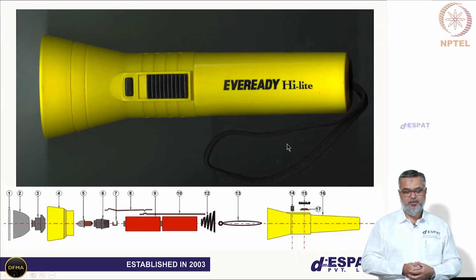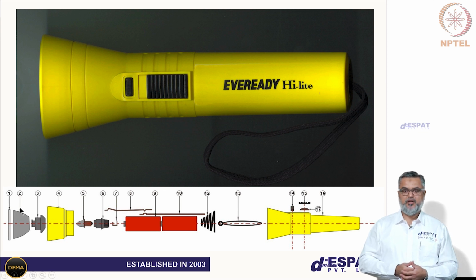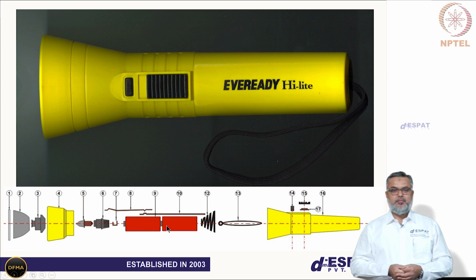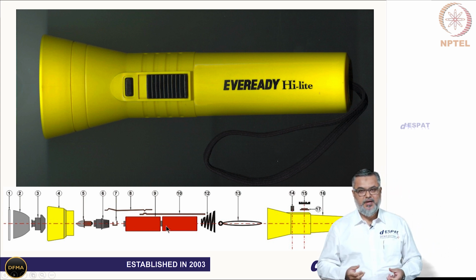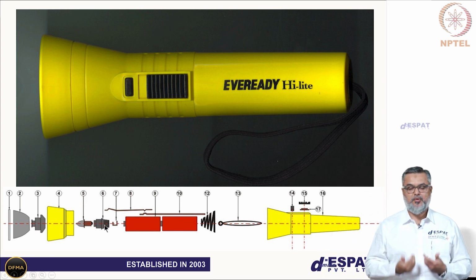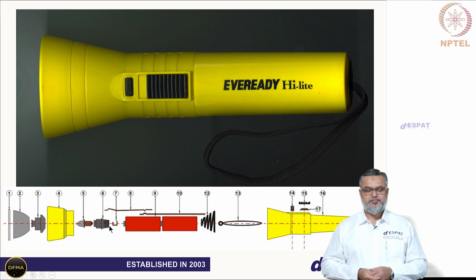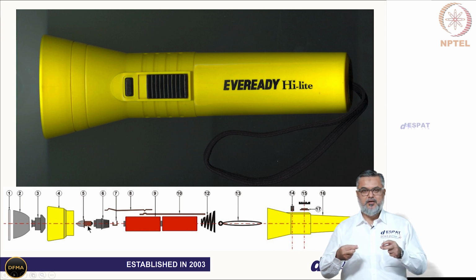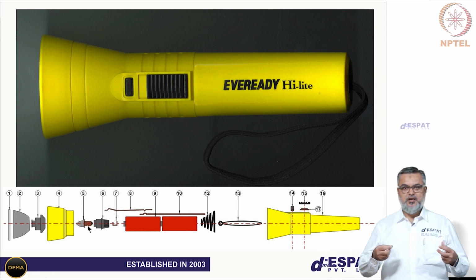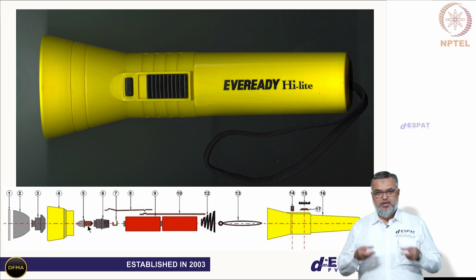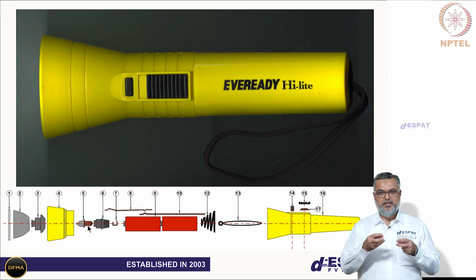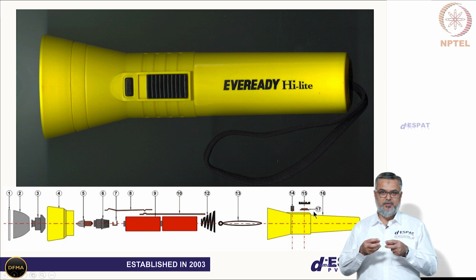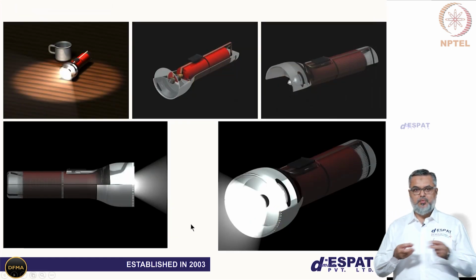Let me take another example here. This is a product that is supposed to throw out light when you touch a button, right. The main functional parts here are a set of batteries, which is a super system which you have to probably buy from a battery supplier, a component which can convert this chemical energy to electrical, and a component that converts electrical energy to light. So, fundamentally if you look at this design, it should have two parts, the one that provides the electrical energy and one that converts the electrical energy to light, but why 17 parts?